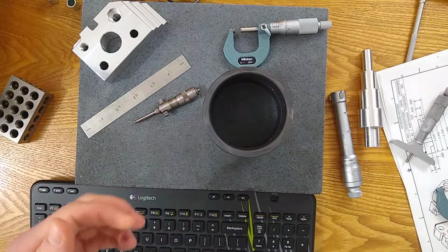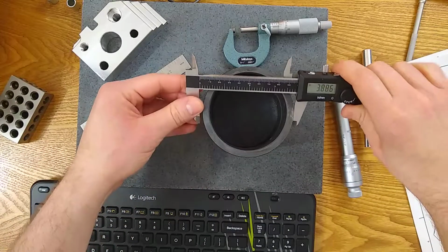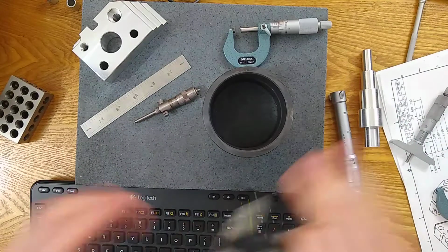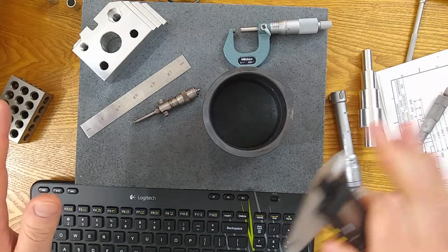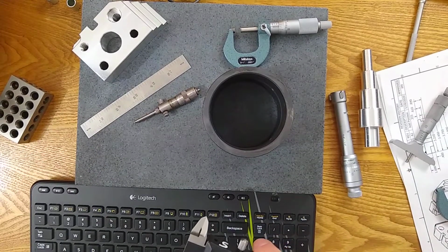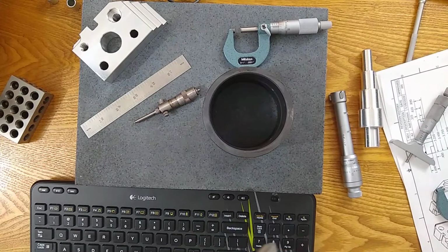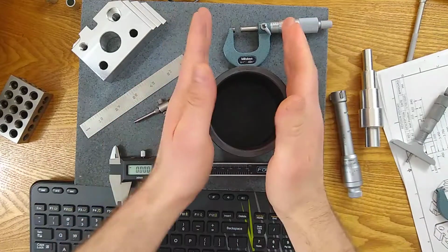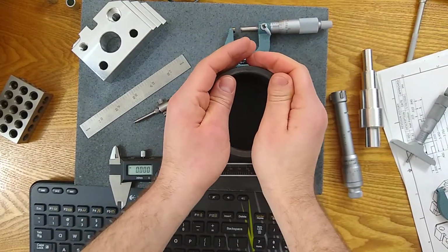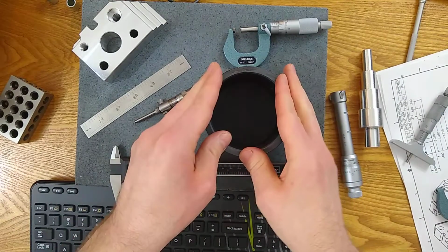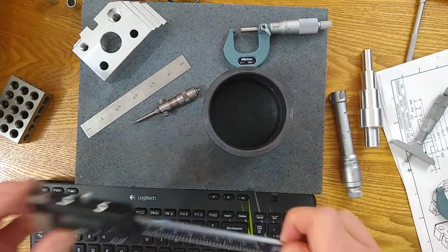Sometimes industry will say, look, you've used your caliper and you verified it's less than the specification. Forget the plus or minus accuracy. But that's not what I want you to do. I want you guys to be thinking and considering your quality, your inspection, even machining, production. You want to be making good parts. So if you're on the edge, you want to verify that you haven't gone out, because it really doesn't matter if it passed your inspection with the gauge you used.